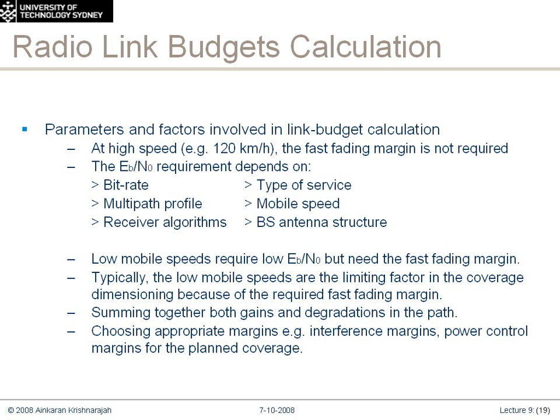So in slide 19 here we have another aspect which we haven't mentioned, which is the speed of the subscriber as well. So the radio network plan, once you've figured out your coverage, your capacity, you understand your environment, you know the propagation losses because of that environment and the coverage and capacity requirements, you've got to then model the subscriber. So what you tend to have are motion models where 3 or 4 models are typically taken into account. There's a 3 kilometer per hour model, so that's somebody walking, for example. There's also, for example, a 20 kilometer per hour model, which is someone being in a bus or a train, that sort of speed. And in very rare cases will you have what's given here, a high-speed model, which is the 120 kilometers an hour.